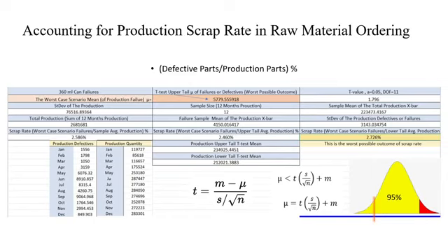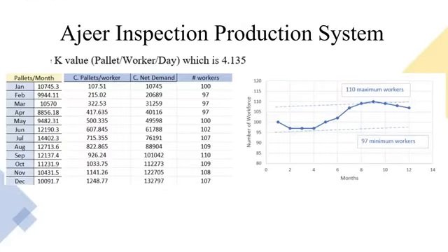So, you have lower production quantity and higher defective parts. When you divide both of these together, you get a percentage of 2.726%. So it's a buffering. We account for scrap rates when we order excess material, which we order more by 2.726%.